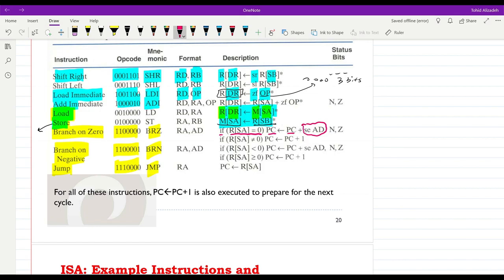So we should go back and have a look at what we had for the jump and branch format. OP code is CM. This is what we have for jump and branch, and we were using what we had here for the address. By combining them, this would give us the offset that we have for the branching or for the program counter.